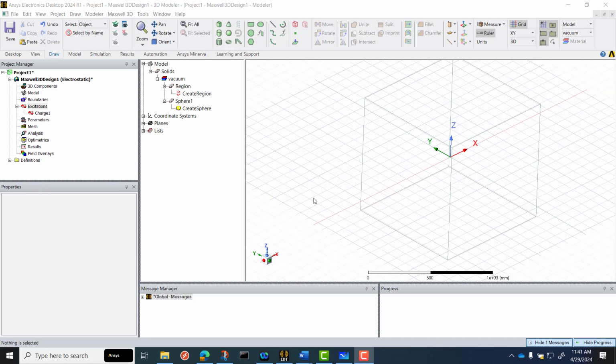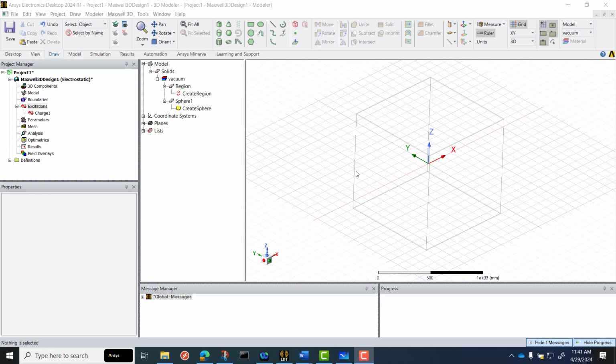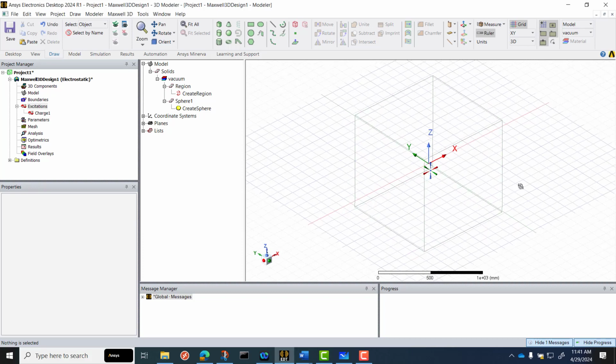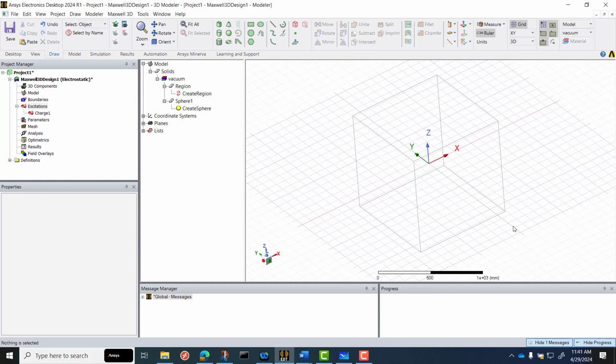Now, instead of explicitly applying a boundary to this new region that we created, I'm actually going to apply another excitation. I'm going to use a 0-volt excitation around the perimeter of that region. So I'm essentially forcing a voltage of 0, which would be analogous to saying in our model of a point charge, the only thing in the universe is the point charge. That 0 voltage condition doesn't really exist until we go out to infinity.